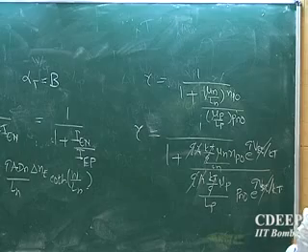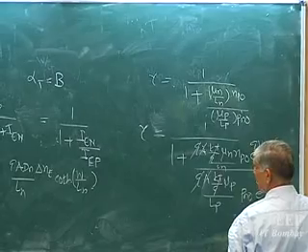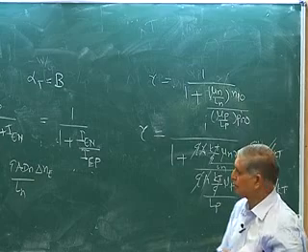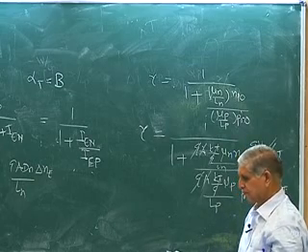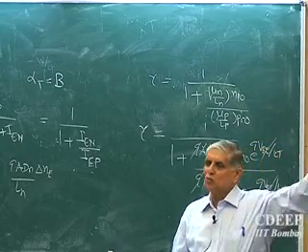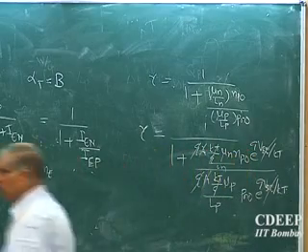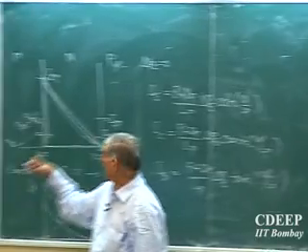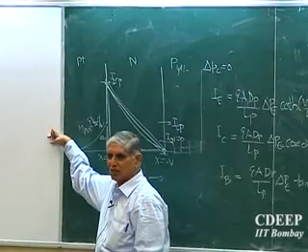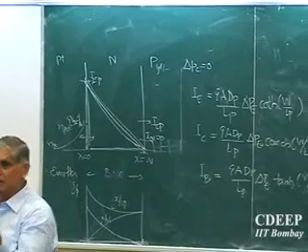Will that coth term also cancel or not? Actually sorry, this term will not appear. Why will it not appear in IN? Anyone? Because for electrons, the length of the emitter can go to infinity. The other boundary, please, this boundary can go to infinite. Is that correct? I'm sorry, I should have said first. Here the base width is very small, so I got W by LP terms.